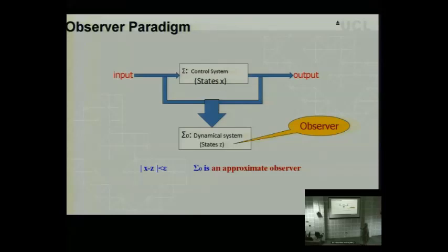They try to approximate the states of the plant using the states of the observer. A classical Luenberger observer comes under that kind of notion, particularly when there is uncertainty present. And for some applications, that might be good enough. We have asymptotic observers, which sometimes can have problems when we get uncertainty.